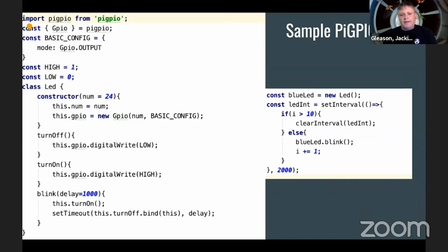So be careful about that a little bit. But you'll see here where on this one I've kind of made more of a class pattern. I've created an LED object that defaults to port 20 or pin 24. Set that to a local state variable, which is kind of unnecessary, but I do it anyway. And then I go ahead and configure the GPIO pin that I need.